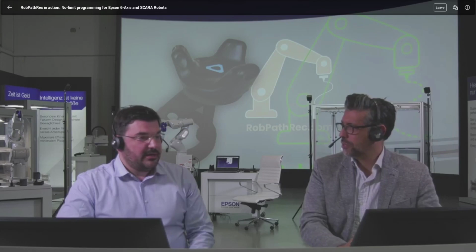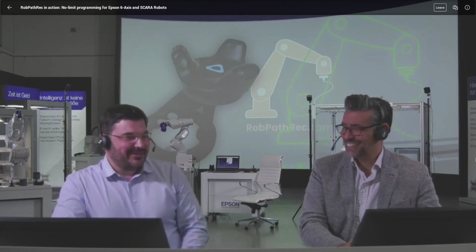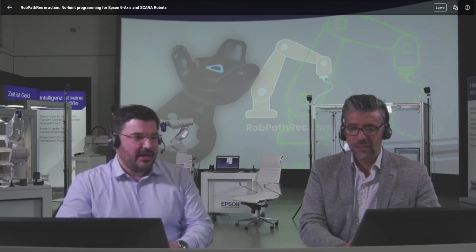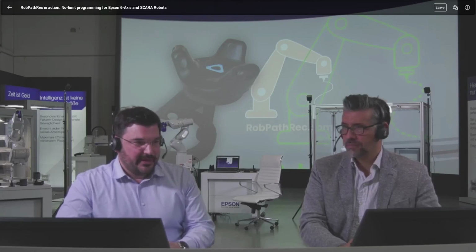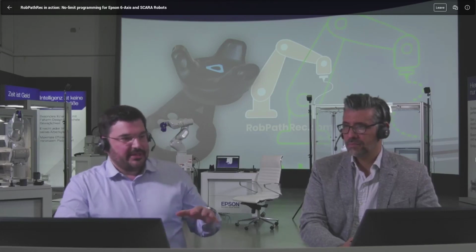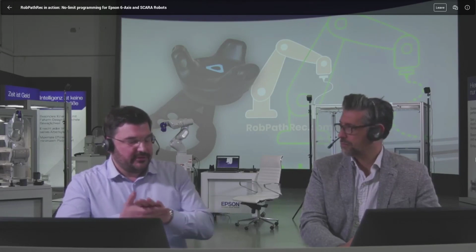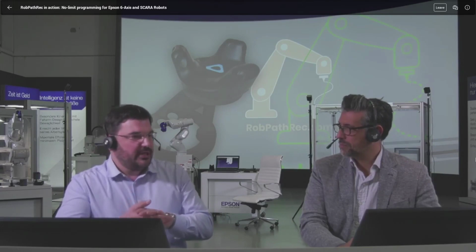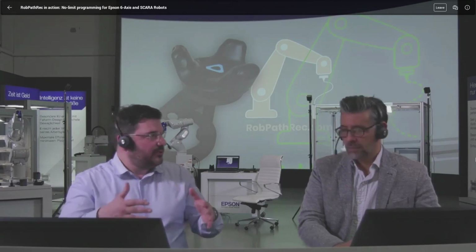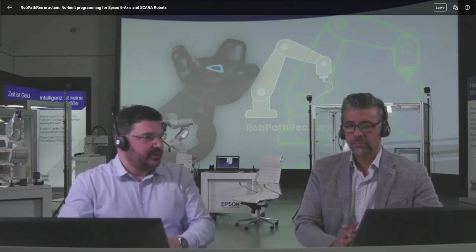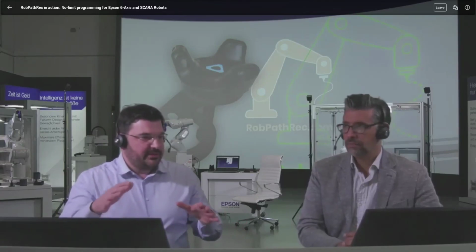can meet the requirements. So basically, we are not working in the base of the world coordinate system of the robot, but we are using the user frame, the local, and therefore in the local you can move anywhere you want. Once the definition or the position to the world coordinate system of the robot is defined, then you are always ready to go. So we are using the user frame, the local, as a base.